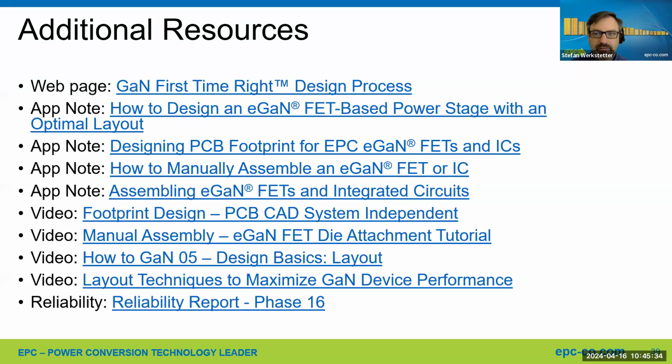Our first question is, what are the symptoms of gate voltage overshoot? So what will be the typical failure? Okay, yes. Our devices have a maximum of 6 volt rating for the gate. And for correct operation, the gate drive voltage needs to be between 4.5 and 5 volts, better 5 volts.